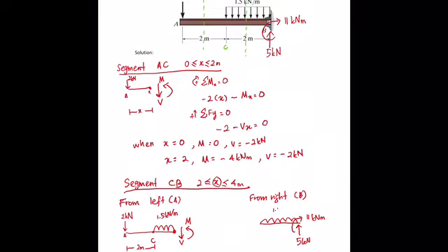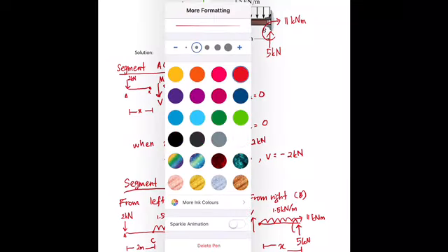So this is 1.5 kilonewton per meter. The distance from here to here is X. So when you cut here, you will expose the internal forces. Please follow the sign convention, which is, if you take from right, V is upwards and moment is clockwise. Okay, so this one